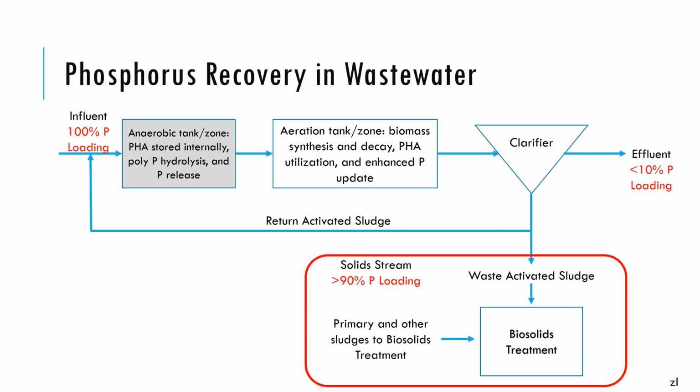Conventionally, most of the biosolids are treated as a solid waste through several steps, including thickening, digestion, dewatering, sometimes with drying or incineration. Recently, people figured out that the phosphorus is actually accumulated in the biosolids and could be recovered from it as a valuable commodity.